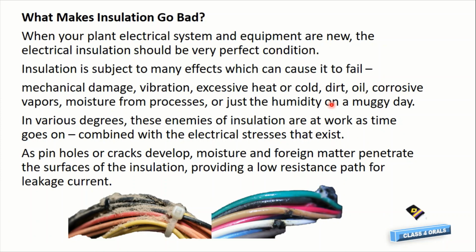Then what is making the insulation bad? We are saying that insulation is good, it is preventing the current from going out, but whenever our system is new, then the insulation is also very new, very perfect, very much intact. There is no leakage, absolute perfect conditions. But by that time there may be mechanical damage, there may be vibrations, there may be heat or cold or dirt, oil, corrosive nature, moisture from around, and humidity on a muggy day. So in various degrees, all these factors are the enemies. These are not good things for any machinery or any windings.